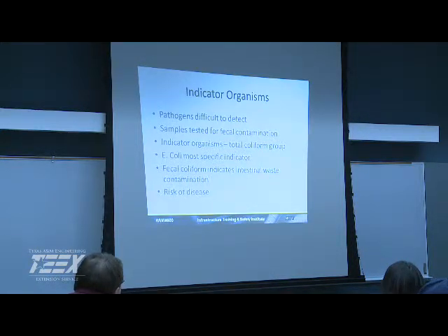The biggest indicator or biggest issue is acute sickness. With disinfection byproducts, we're looking at chronic illness, being exposed to this over the long term and winding up with cancers and stuff like that. The thing about waterborne pathogens is you're going to know it pretty quick. You're going to know within 24 to 48 hours if you've been exposed, because you're going to have a lot of people. And that's what happened in Milwaukee.